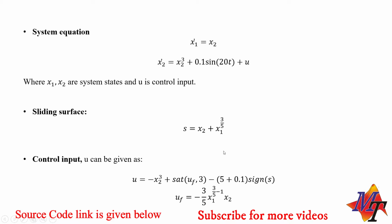Basically, when we differentiate this sliding surface, we can get this function also, but we are taking saturation of it to avoid the singularity problem in our control technique. Now we will design a Matlab Simulink diagram for the same system equation, sliding surface and control input, and for the reference we have linked the reference paper in which this whole system, sliding surface and control input are presented similarly.